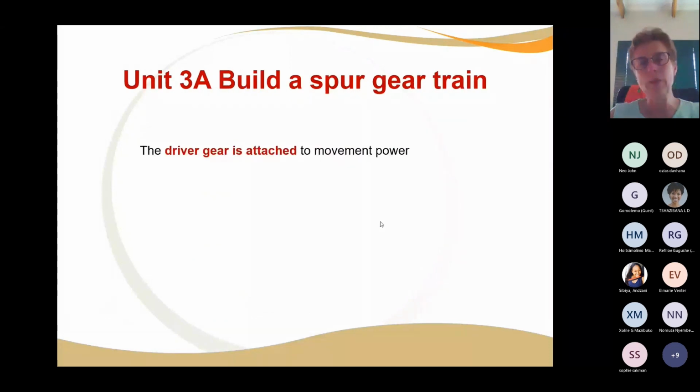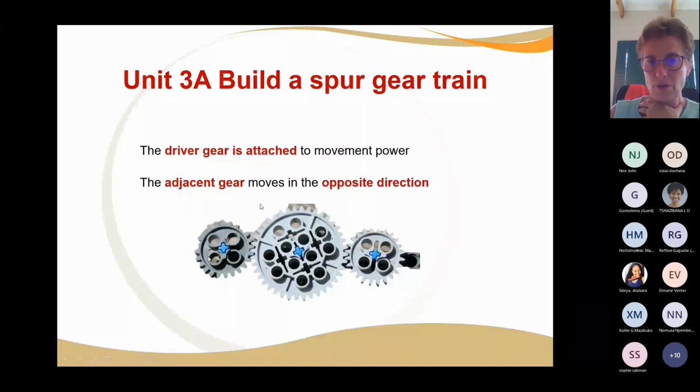All right. So basically, when you're building a spur gear train, you've got a whole lot of gears in line, and that's what I said. So if these are all spur gears, different spur gears, but you can see they're all meshed very well. There's a meshing and there's a meshing. So the one moves across every second. So if this one goes clockwise, then this one will also be going clockwise because this one will be going anti-clockwise.